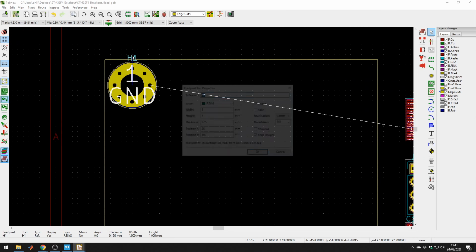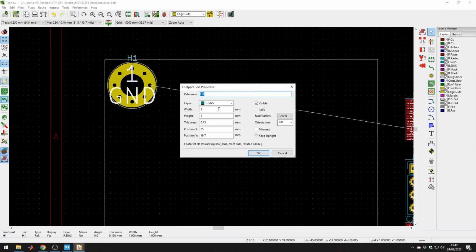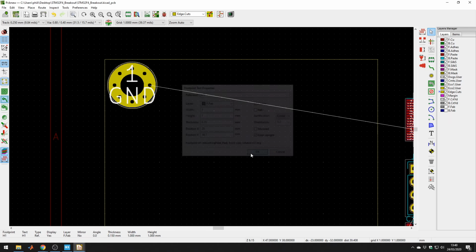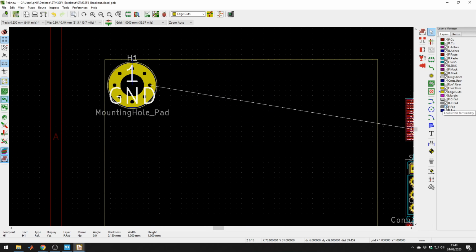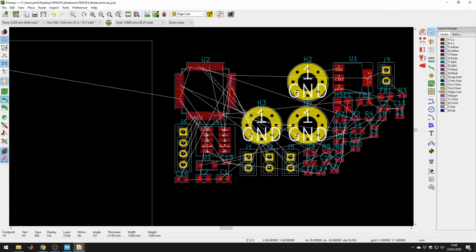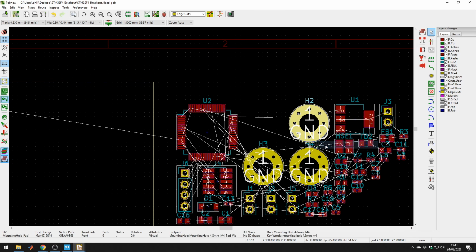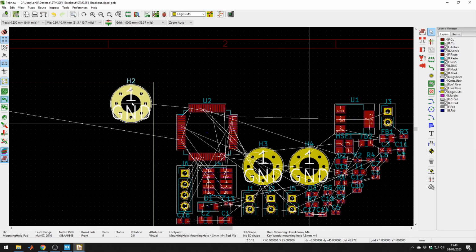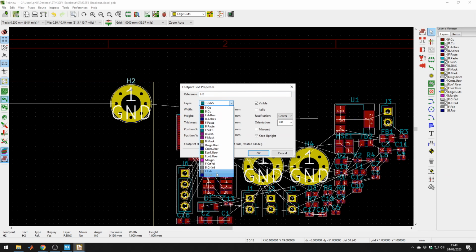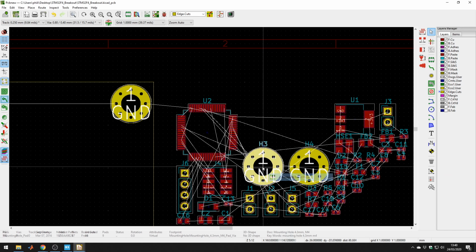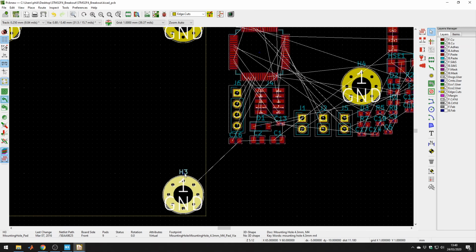So what I do is double click on the footprint text and move it to the fabrication layer. So they're still there if you need it. If you click FFab, you can see the designator. So that's how I do it. Okay, so let's just go through all these. You'll see they'll align nicely. FFab. It gets a bit tedious moving these, but you know.